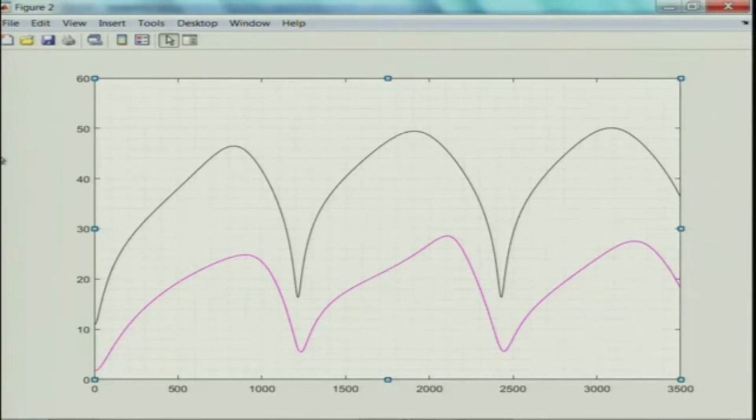So, which one is correct? Well, I am not quite sure here, to be honest. One thing is for sure, that we need to use the more modern expressions, because they have been obtained by much more accurate mathematical models, and they have been corroborated quite well experimentally. So, I would trust the predictions based on modern expressions for perforate impedance more, at least for cross flow configurations when mean flow is present.